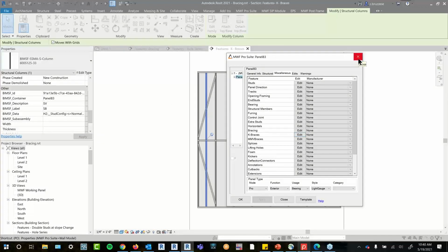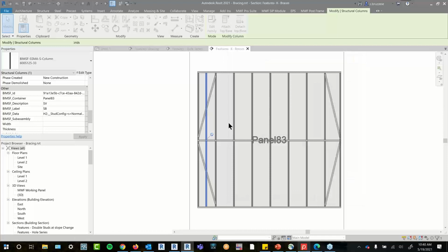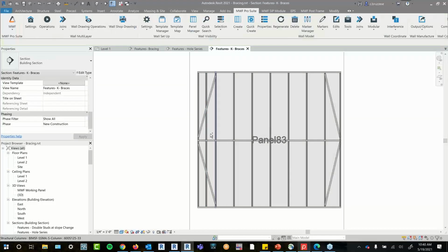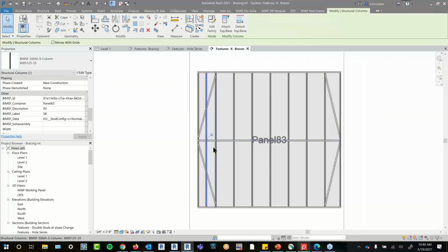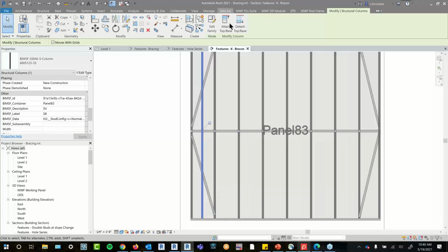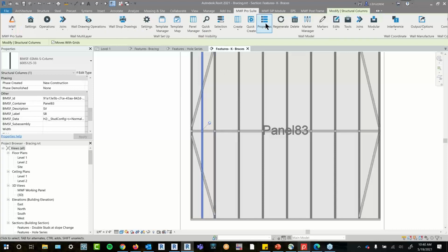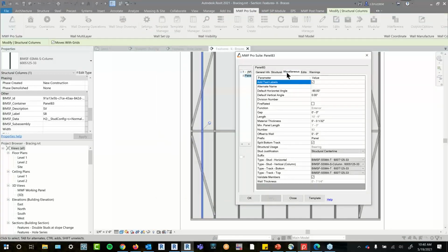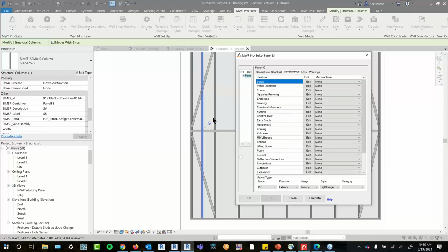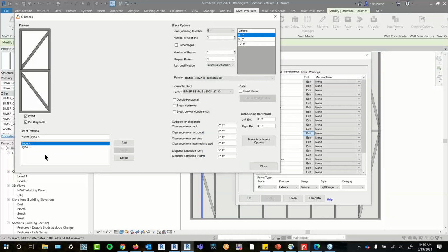It depends how you added in the vertical element. If you just do a straight copy paste, then you just have to add that as part of the panel so that it recognizes it within UID. So the main thing I would say to adjust is, even though I'm adding in a new vertical member here, my K-bracing in the actual properties itself should start at the leftmost member, but now it's got S8 in here.